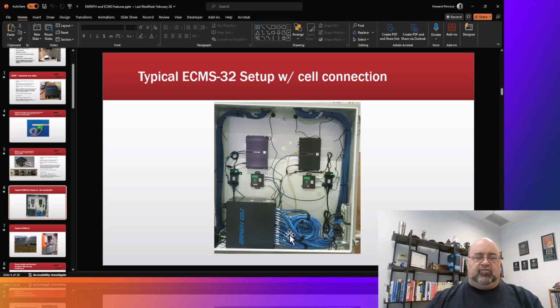Ethernet has a range of 105 meters. In a recent presentation by somebody else, they said 105 feet. That's incorrect. It's meters. That means well over 300 feet. So 320 feet. After that, we see a minor degradation. We have installed as far as 1,000 feet away, and that is length.